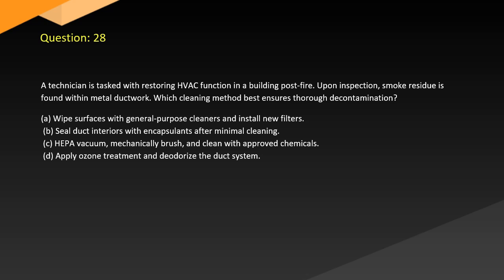Question 28. A technician is tasked with restoring HVAC function in a building post-fire. Upon inspection, smoke residue is found within metal ductwork. Which cleaning method best ensures thorough decontamination? A. Wipe surfaces with general-purpose cleaners and install new filters. B. Seal duct interiors with encapsulants after minimal cleaning. C. HEPA vacuum, mechanically brush and clean with approved chemicals. D. Apply ozone treatment and deodorize the duct system.